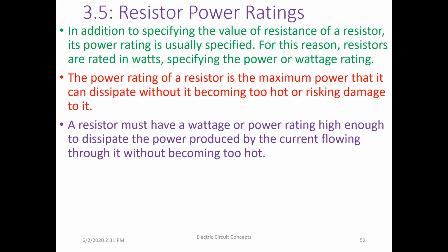The power rating of a resistor is the maximum power that it can dissipate without becoming too hot or risking damage to it. A resistor must have a wattage or power rating high enough to dissipate the power produced by the current flowing through it without becoming too hot.